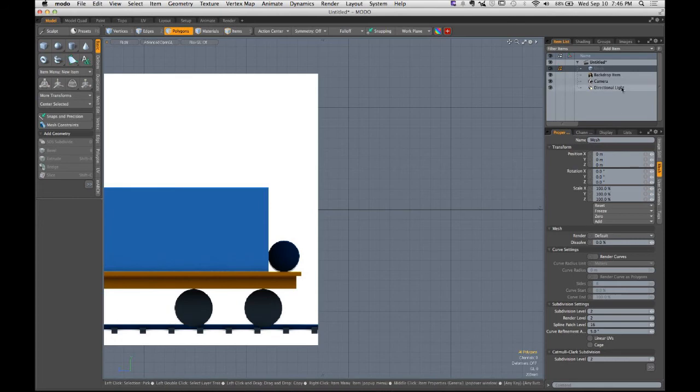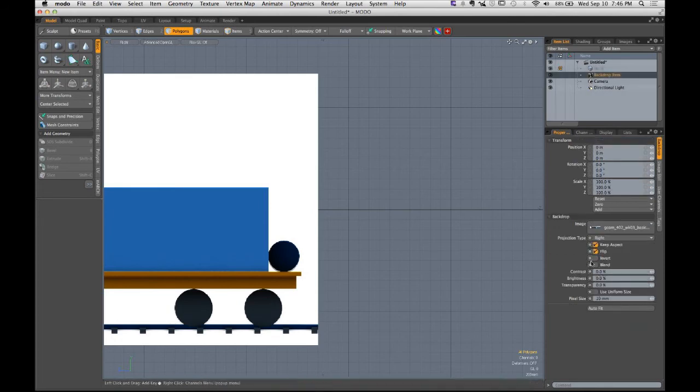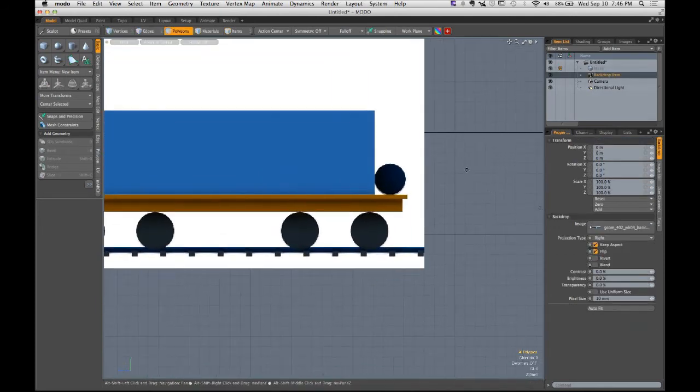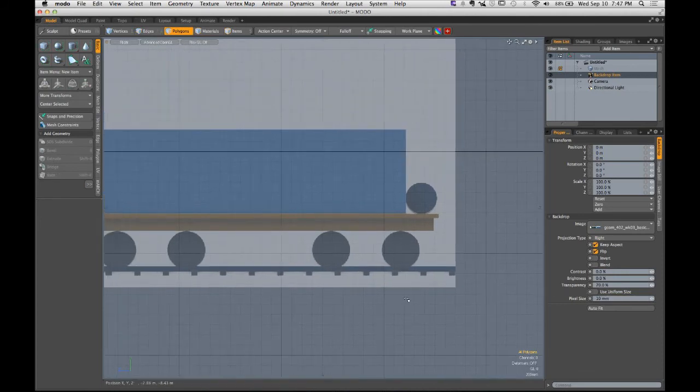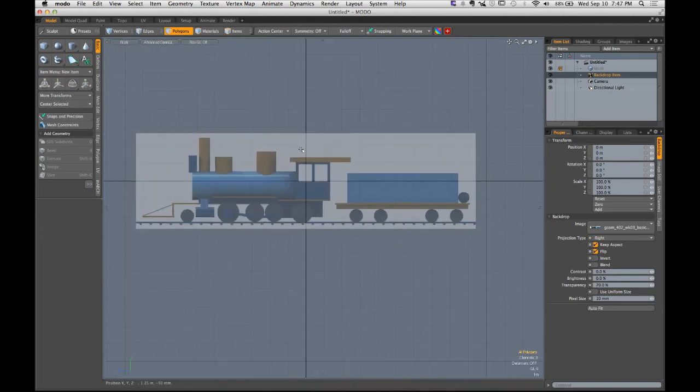Check it out. Backdrop item. Look, we have a transparency value that we get to adjust. I want to increase it to about 70%. It's going to make this image kind of ghosted. Hit the return key. There we go. And now I can see the grid lines behind the image. Step number 1 done. Step number 2, we got to move this thing.